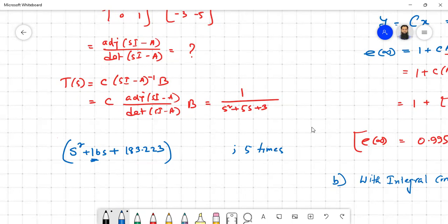So we can assume that the pole is far away, and s plus 100 can be one of the candidates, which is more than whatever is necessary. Five times away should be good to go, that is 5 into 8, so 40 should be good. But we are on the safer side, just following the example given by the book. As long as it is 5 times 8, it should be okay.